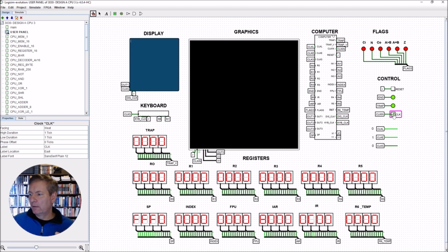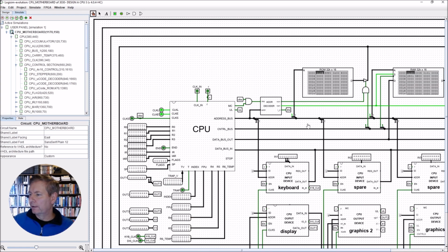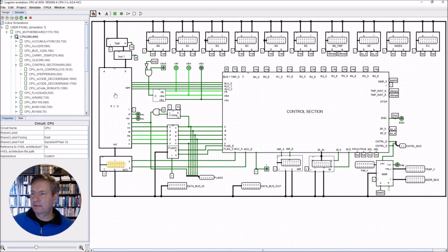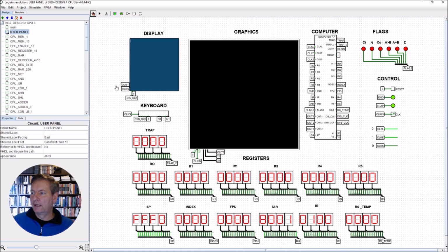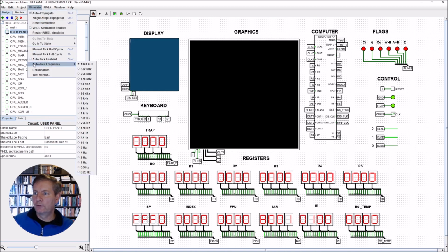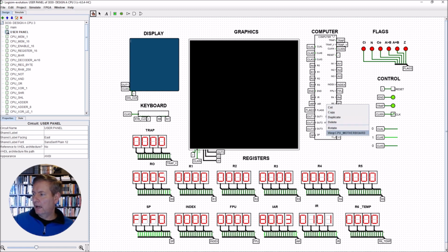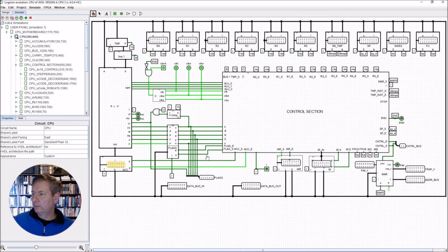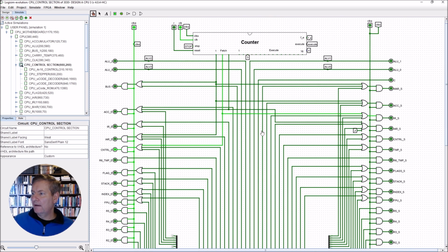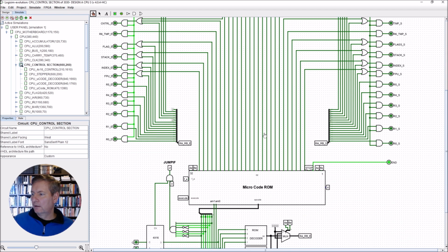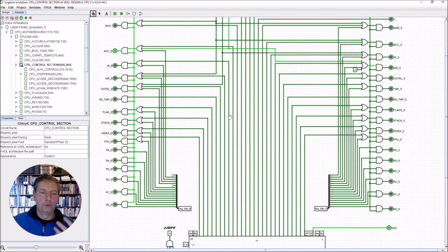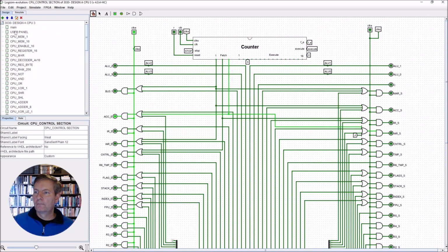At any point in time I could drop down in and have a look and see exactly where the machine is and what state it is in. If I want to, I can also run it very slowly, so I can go tick frequency and put the tick frequency very low and go simulate tick enabled, and this will tick through, and as it ticks through we can drop into the machine and watch every single pulse that generates in order to make the code run.